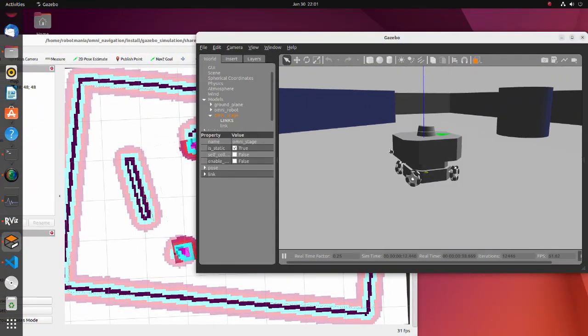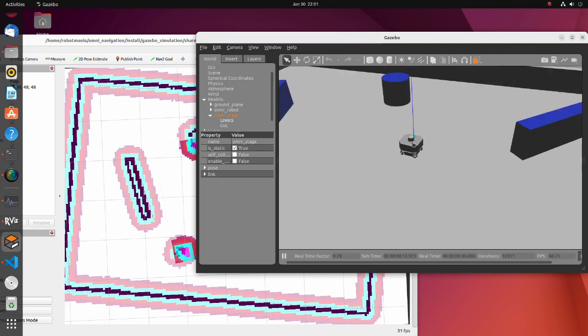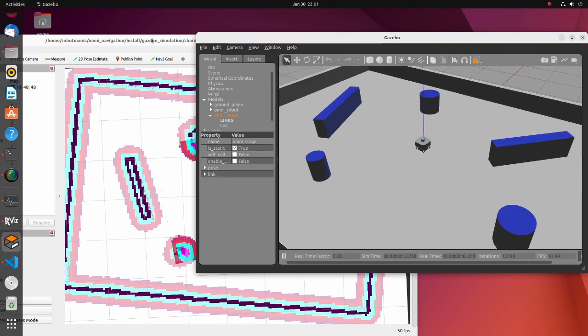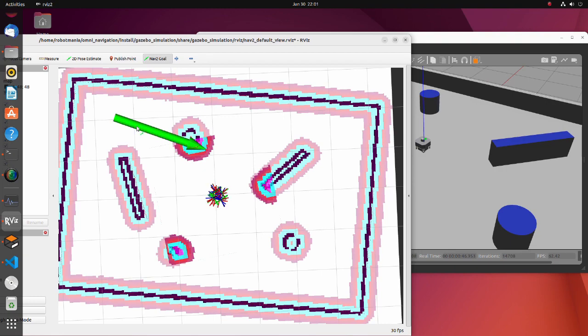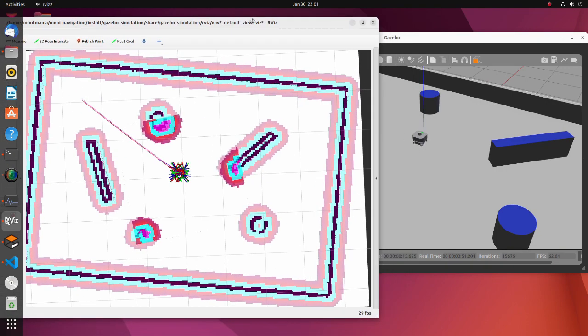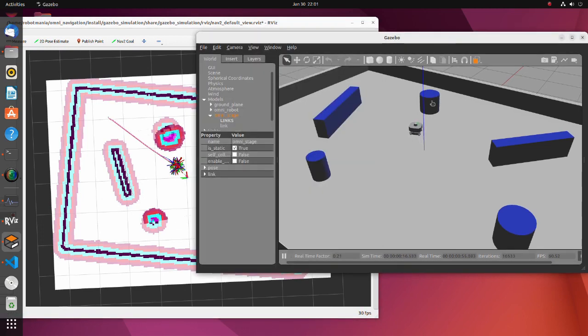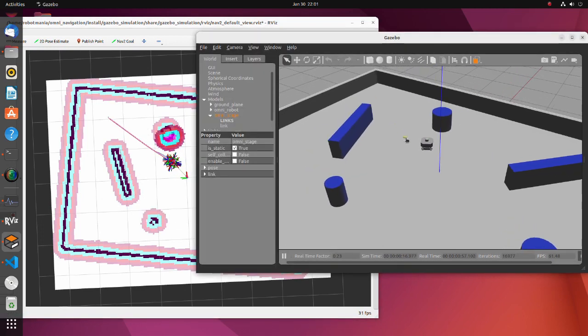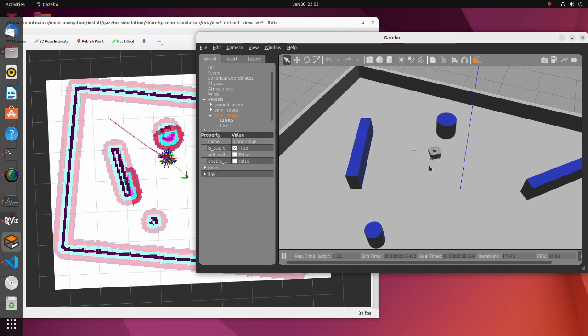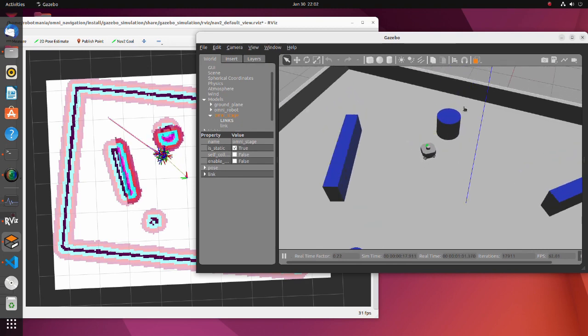In this tutorial we will do Omni robot navigation using Nav2. For robot control we will use ROS2 control. In this project, as a sensor, we are using only a 2D Lidar. This means that both odometry and self-location are calculated based on scan data. This method can be implemented to various robots.